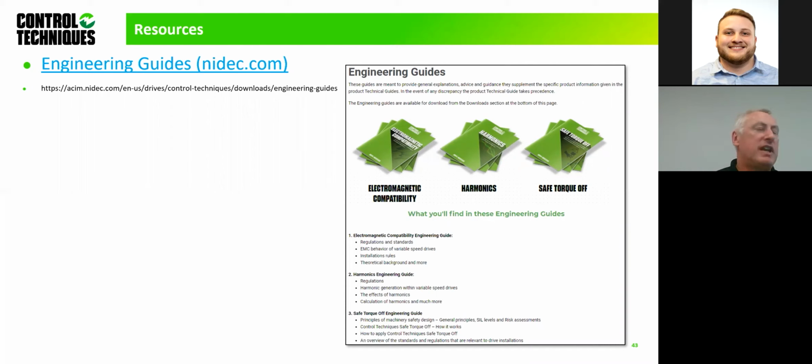especially for a generator. Now, in an existing installation where they've got current problems with transformer distortion, where they may have 2 supplies, 2 transformers feeding a constant running machine, and the point of coupling at MV is interfering with a residential estate, etc., you could change the transformer configuration and do a pseudo 24 pulse on the supply transformer, and not touch the drives. Okay, so there's different ways of engineering a solution on a power supply.